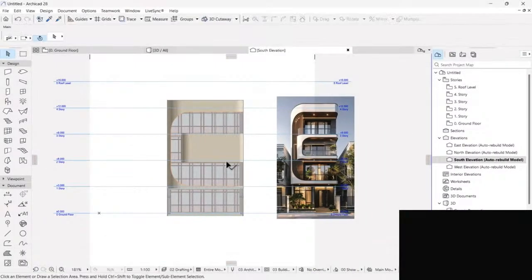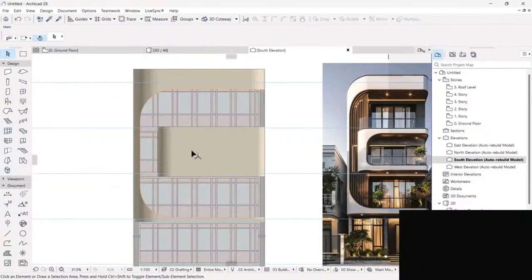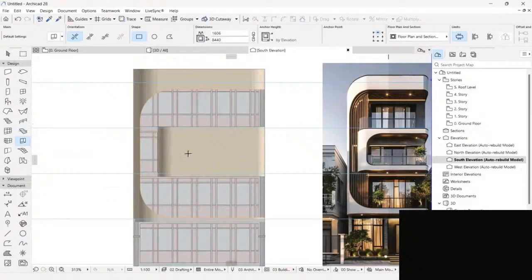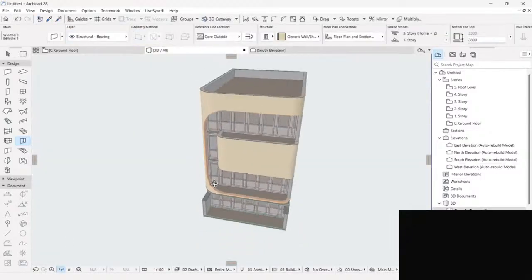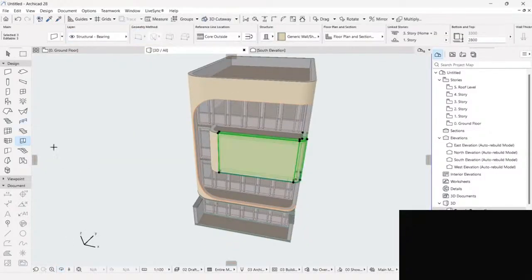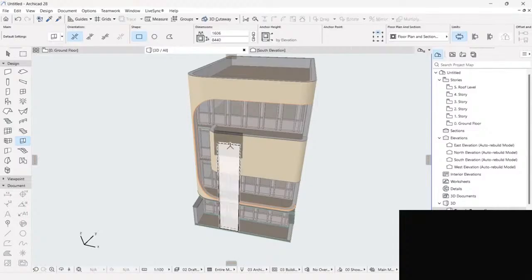Okay, perfect. So it's the time for us to place the cutting by using an opening tool. I'm gonna select this one. Okay, let's best do it on 3D. And opening, I'm gonna pick that.